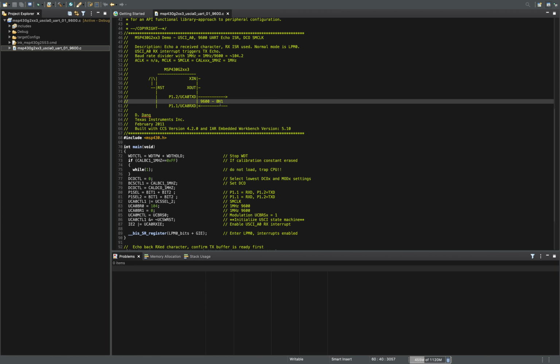We need to know that because one of the things you'll talk about in class is how we don't share a clock signal across the two devices talking. So things like the bit rate is very important to be able to effectively know what's being said. The 8N1 is other configuration things that we'll worry about later in class. And I'll show you how to set them up, or I'll show you what they mean just in the briefest amount in a second when we go over to look at the thing actually physically working.